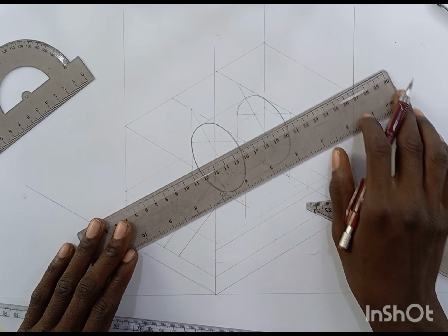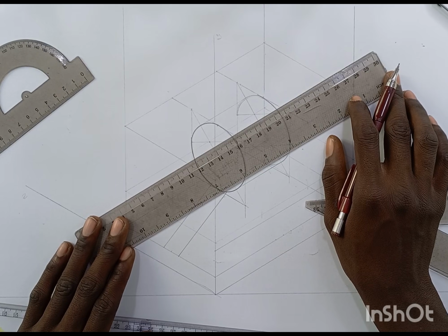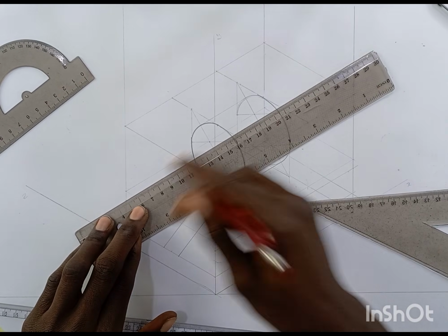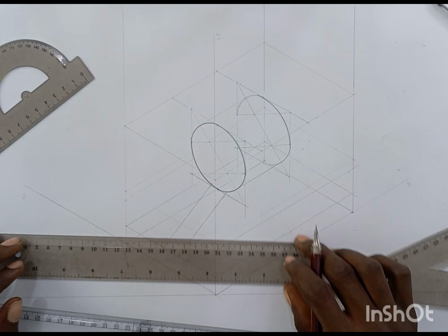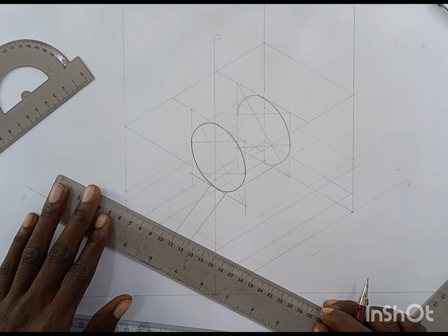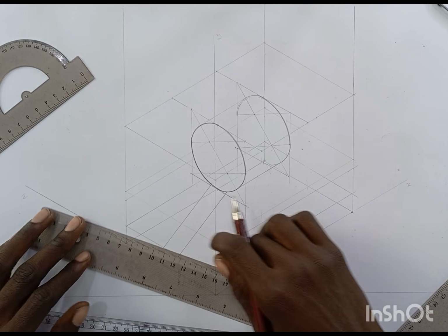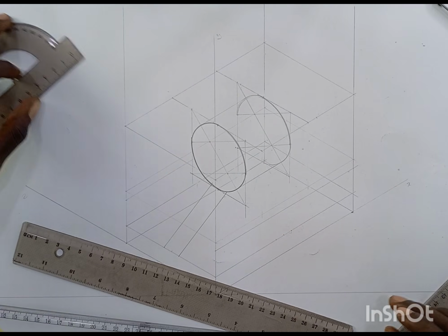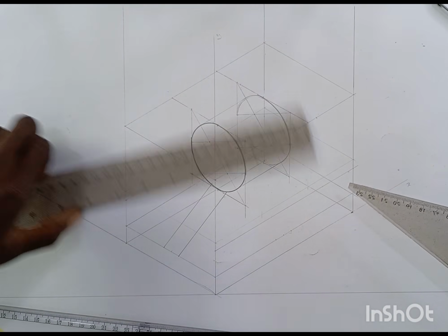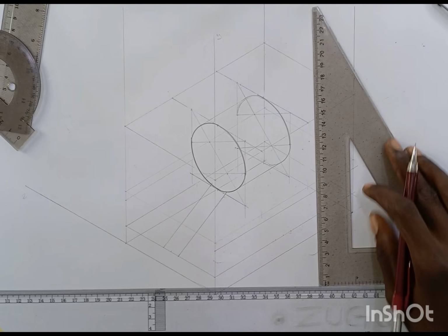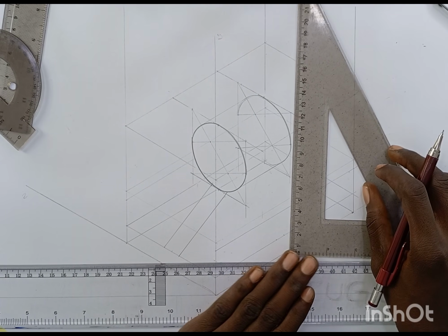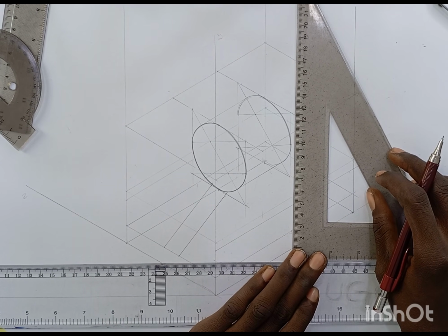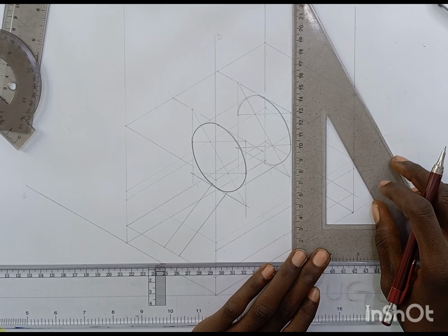But since the cylinder at the top is covering the rest of the lines, I'll just stop immediately where it touches the cylinder, like this. I don't need to prolong it. And also, the next thing is I don't have to connect this point 22 because I don't need it anymore. So now I will project these two points upward before I take my slanted line. So this point, I will take it upward, touching the line 22 that we drew. This is it.